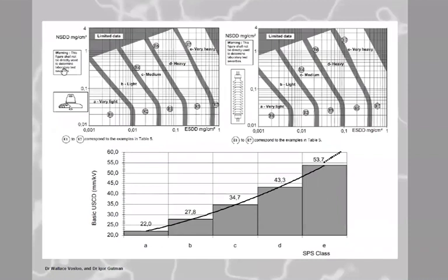And then you can see now you measured your non-soluble deposits and your soluble deposits, which is now your equivalent salt deposit density values. And from here, you can determine the pollution severity levels in your area. If it's a very light area, very light, you need 22. And if it's B, which is now light, you need 28. And now you see these values are far higher than what we were used to because of the square root of 3. Square root of 3, the little bugger came around and bit you right on the toe, because that's where you make your mistakes, okay?